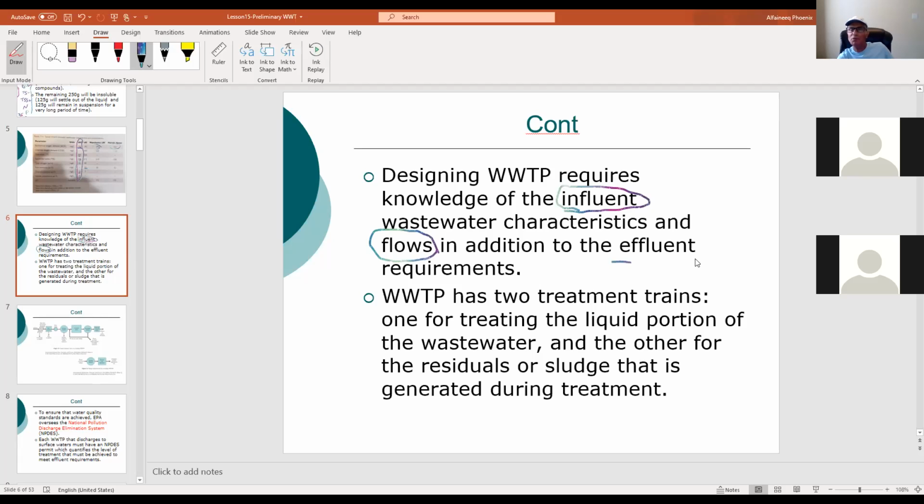And the effluent, what are the recommended values? We'll look at them now. Are you going to go with 30 milligrams per liter BOD or 20? Or maybe you're going to go advanced. If you want advanced treatment, this number must be lower, maybe 5 or 10, depending.